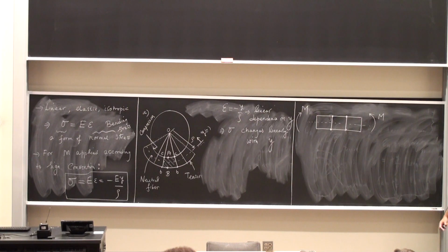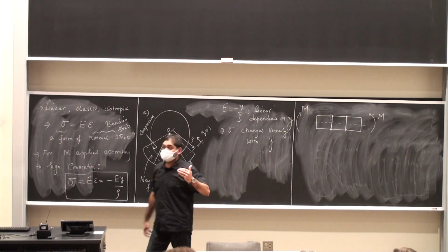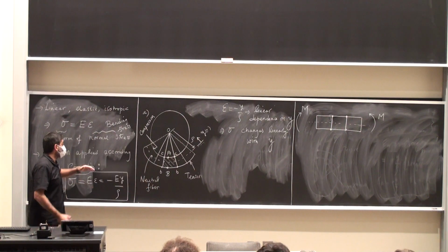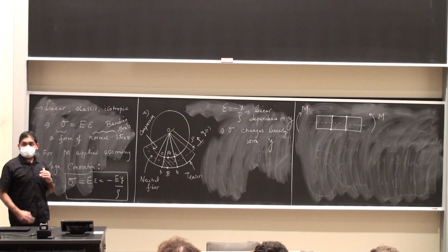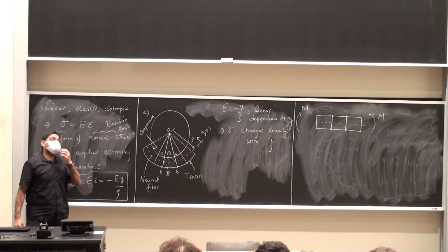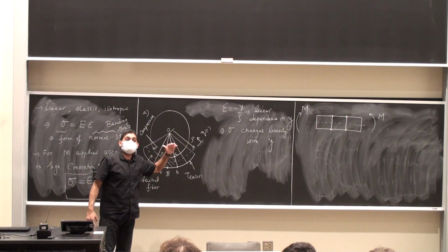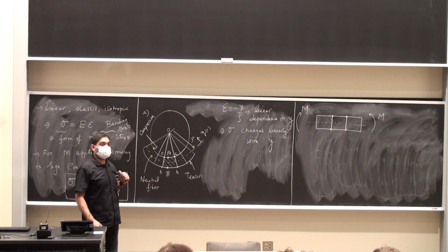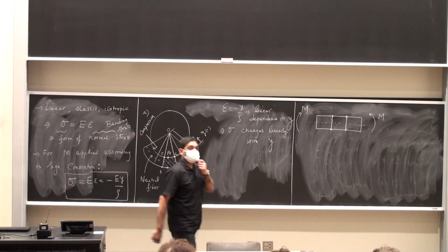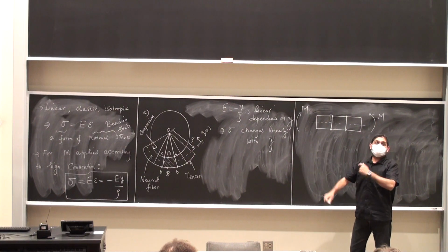Epsilon is the largest on the top and the bottom, as you can very well see, if you have a rectangular cross section, because they are farthest away from the neutral fibers. The stresses, if they are linearly proportional to strain, also have to be the largest at the top and the bottom. It is just that the sign of the stresses will be negative at the top, positive at the bottom. So if I draw the stress distribution, it's going to look like this. The arrow on the top is going to be the largest of the lot.